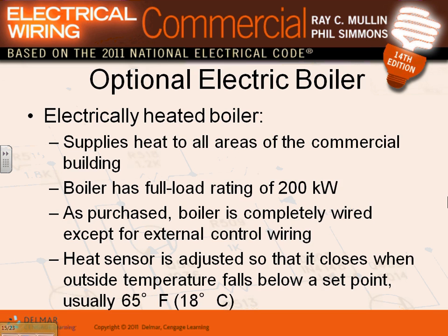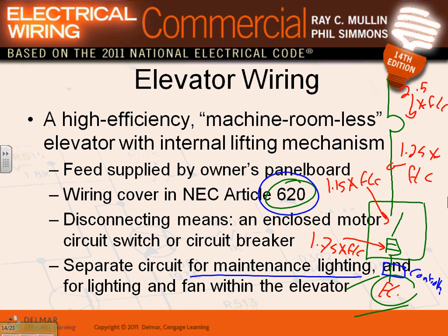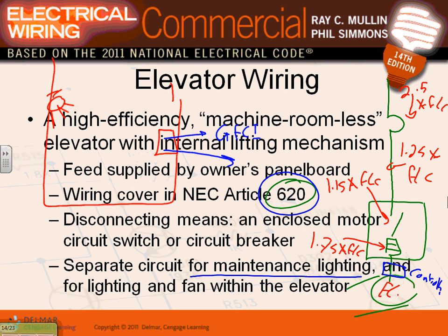Electrical boilers, okay. Another thing you need to be aware of is, actually, inside the pit, at the bottom of the elevator, they want you to put a receptacle here and a light. So we have to have a receptacle. This is GFCI, bring a circuit to it, and this is the light. And this is my pit here.